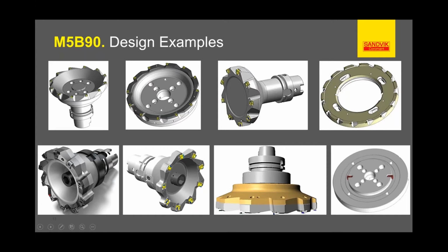So anyhow, this is quickly becoming our go-to solution right here, because it reduces mass, it's easier to balance when you're running super high RPM, better for the tool changing operation to reduce weight, that kind of thing.